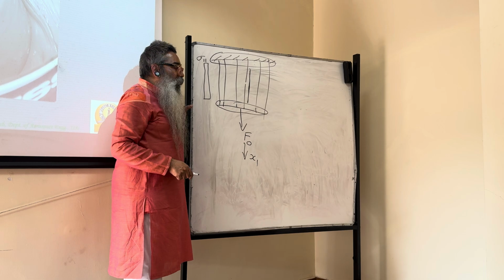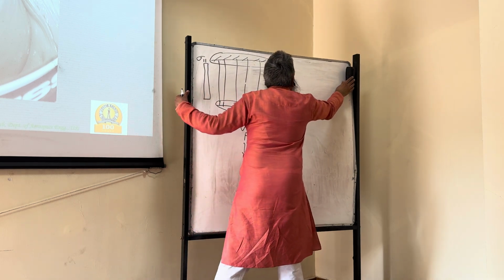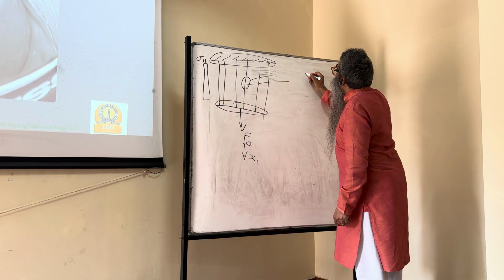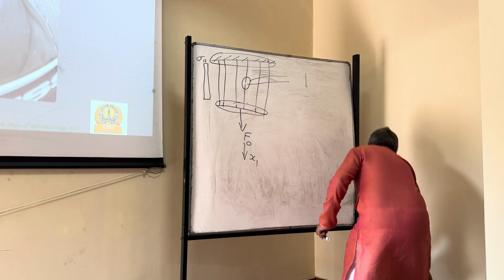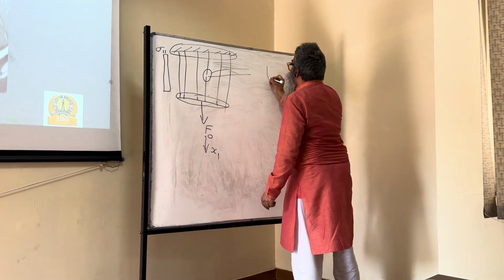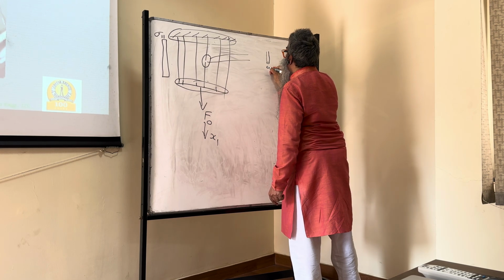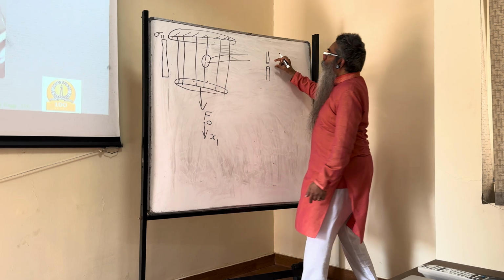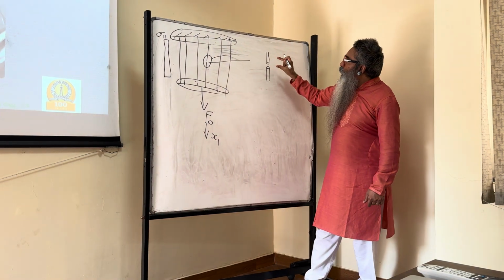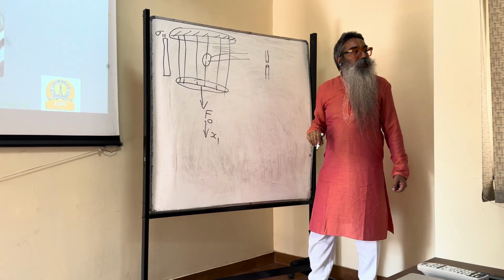Now what we have is a situation where we have the matrix inside. What happens is that where it is cut, if I draw this particular portion in an enlarged way, I'm drawing the separation in an exaggerated way, but to start with it will be almost in contact, and then slowly, because of the load that is there, there might be a slight separation, but it's of the same order of magnitude as the diameter of the fiber.